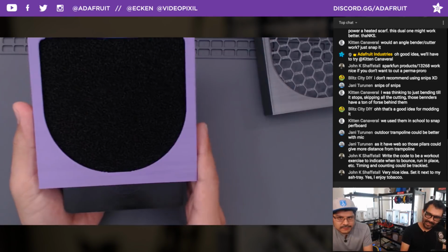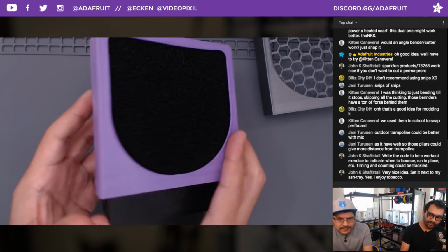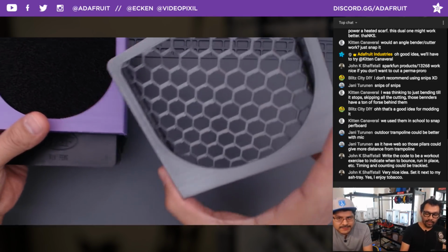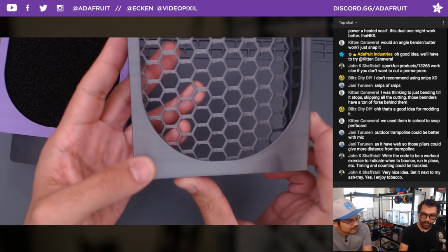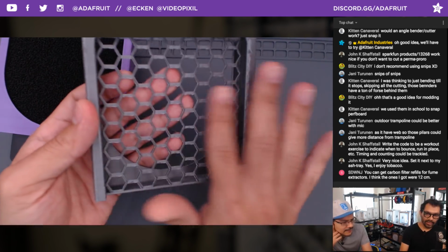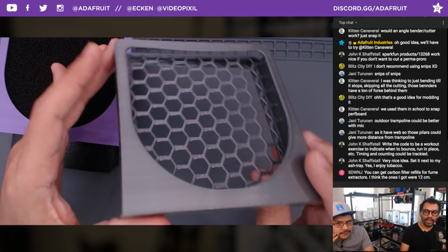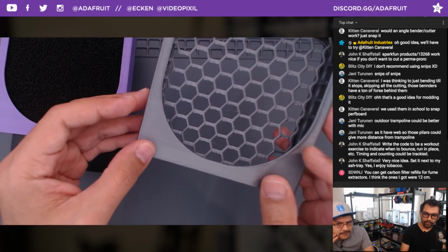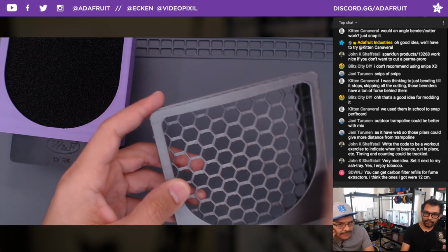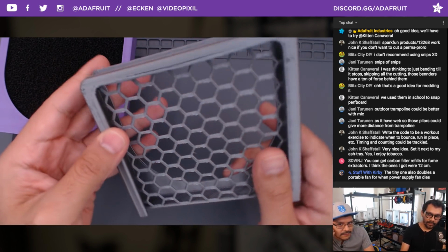So it's an interesting little shape. Prints upright. It's a great use of the 0.8 nozzle, so you can print it in like 30 minutes. This thing printing in 30 minutes still blows my mind. It printed so fast, with a good retraction from the Ultimakers as well. It's all one piece too. A little bit of a bridging challenge, but your printer can do it with a nice active cooling fan. Not too bad.